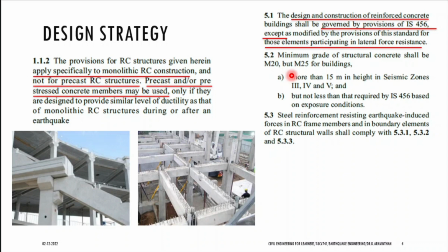That is the difference. In high performance concrete, they use additional 2 or 3 ingredients. You only add 4 ingredients. What are they? Cement, sand, fine aggregate, coarse aggregate for making a concrete. But for high performance concrete, at least 2 additional materials are being used. They might be fly ash and one chemical admixture. So with this, these are the ingredients of making high performance concrete.